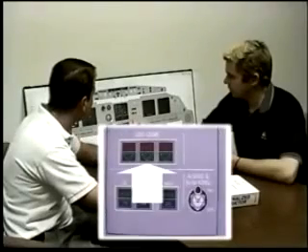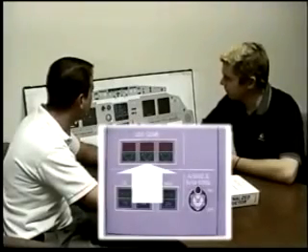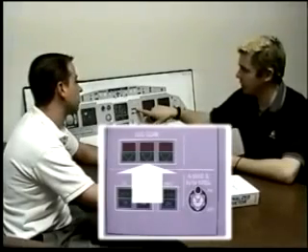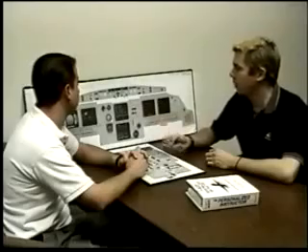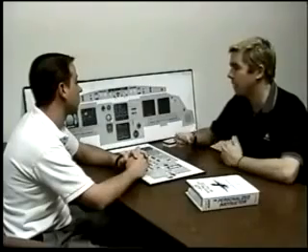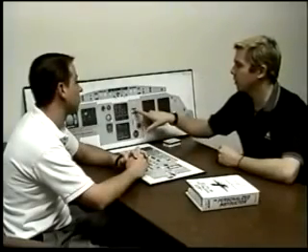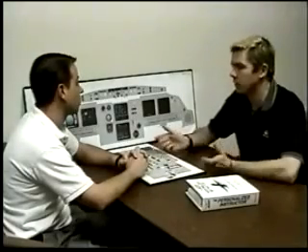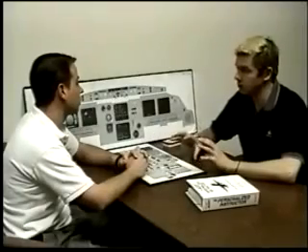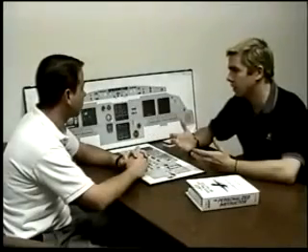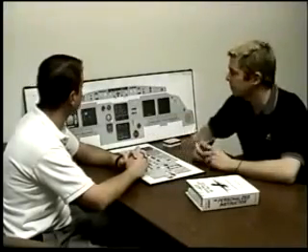Landing gear panel. Talk to me about some of these indications that you find on the landing gear and where they are coming from. Okay, the landing gear indications on the forward panel right here are coming from LGCIU-1. The signal is sent up through LGCIU-1, which doesn't really process it. It just basically passes through and then displays information here. On the ECAM, though, we've got two indications. One of them comes from LGCIU-1, the other from LGCIU-2. They're independent. They go through the LGCIUs, are processed, and then passed on to the ECAM. LGCIU, by the way, stands for Landing Gear Control Interface Unit.